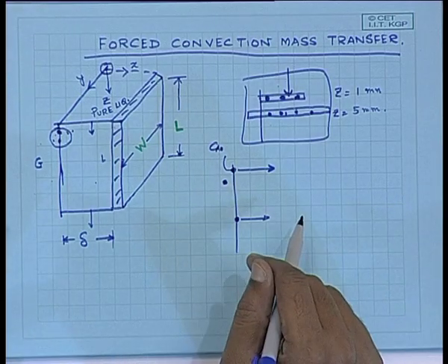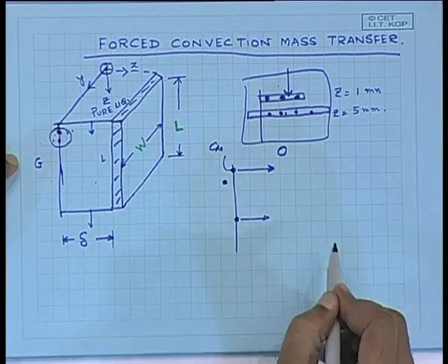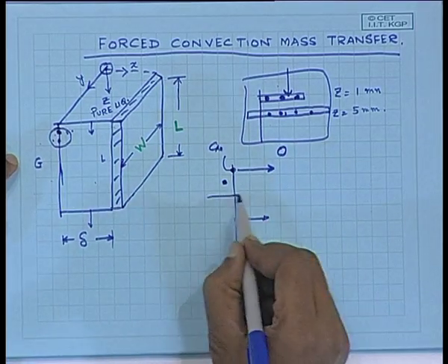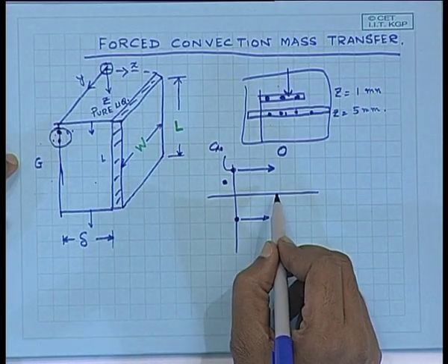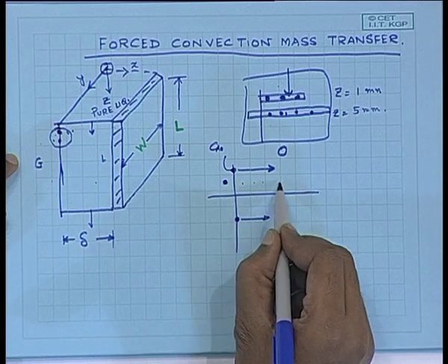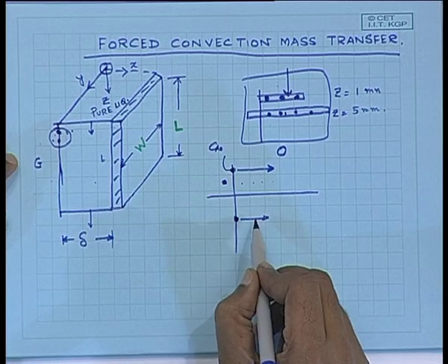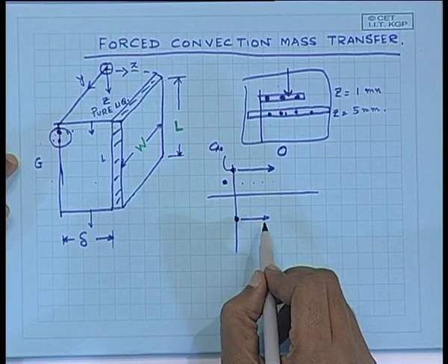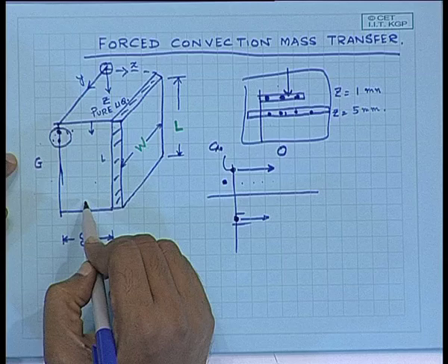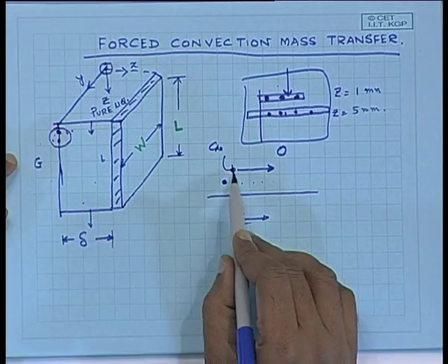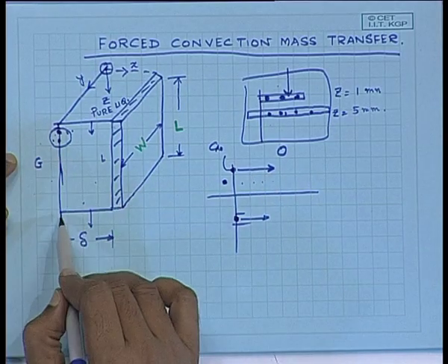Why not? If no, why not? Think about it. You start with 0 concentration of the gas at the top, but when you are, let's say, at this point, this liquid has already some gas molecules in it, distributed inside it. So when you come to this point, the gradient, the driving force is going to be slightly less. So less amount of gas is going to get absorbed per unit length as I move down in z. So your rate of gas absorption will decrease as I move in this direction.